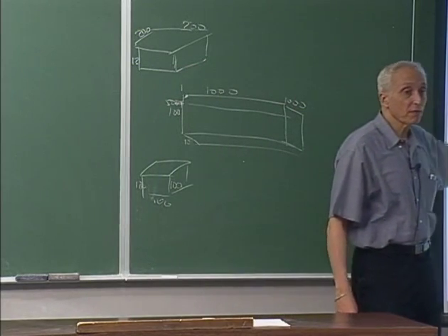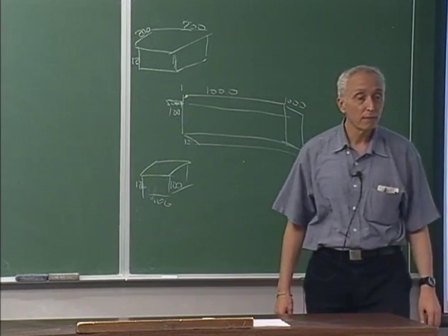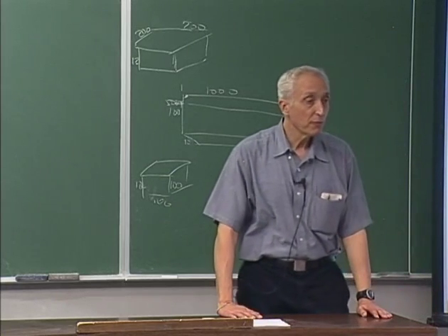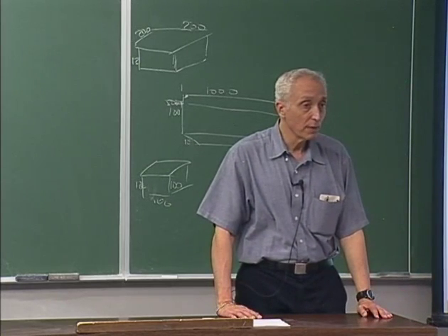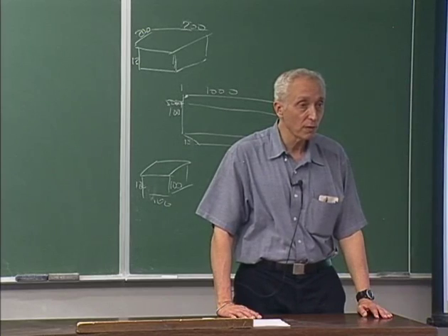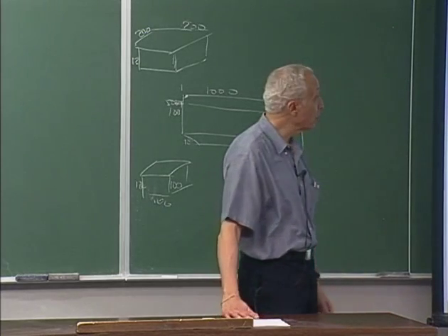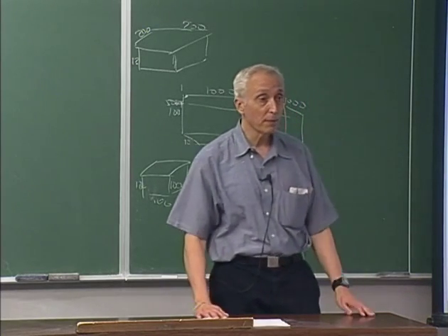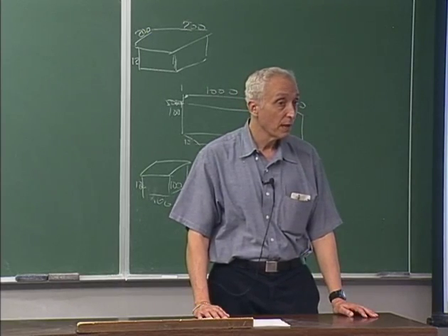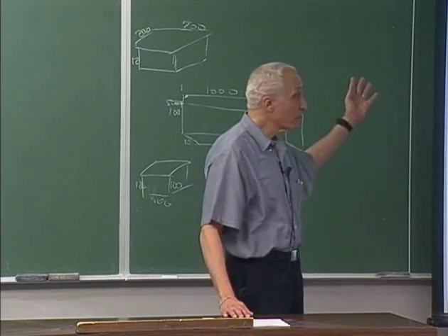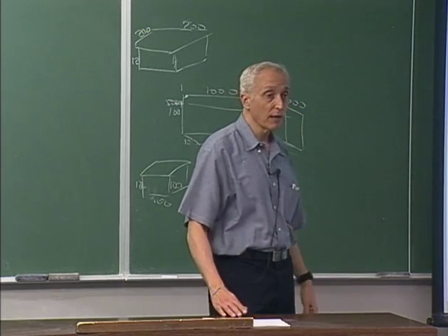that this is the standard way to calculate either vibration frequencies, and then μ will be the square of the vibration frequency, or buckling loads, and then μ will be the amplitude of the buckling load. And this is called a generalized eigenvalue problem.